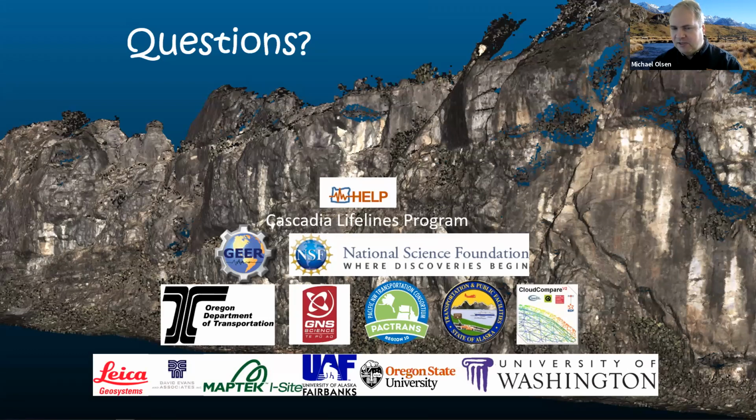For rock slopes, the thin plate spline method over a localized area tends to work really well, because it follows the curvature of the slope, compared to something like a Delaunay triangulation or inverse distance weighted and those kinds of things. The big challenge with thin plate spline, though, is you have to apply it over a very small window at a time, because it's computationally very intensive, given the matrix math involved.